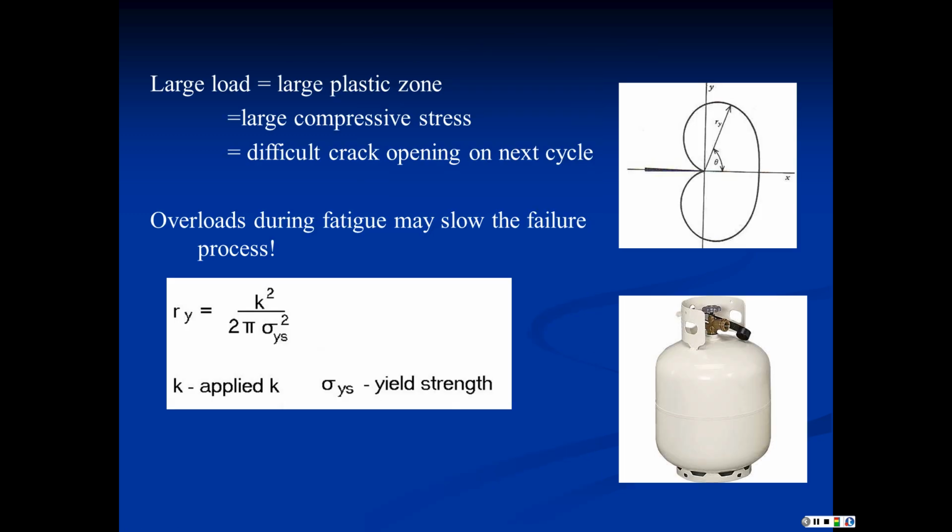Let's talk about a real application for some of these ideas. So if you think about these nice propane tanks, right? One of the great gifts to the griller, because you can go home after work and throw something on the barbie real quick. And you think about how these are used. They're a high-pressure vessel. They are loaded with an explosive gas. They're stored in garages and what have you. And when you do that, you get cyclic loading because of the temperature fluctuations in the garage. As it heats up, the pressure in the tank rises. As it cools down, the pressure drops. So the tank sees a cyclic load.